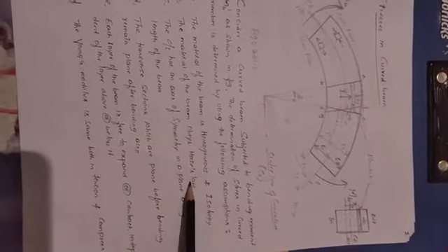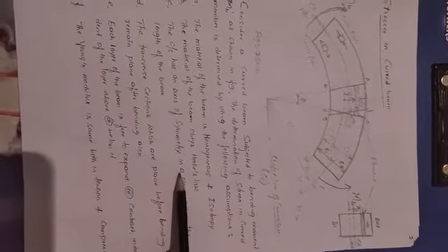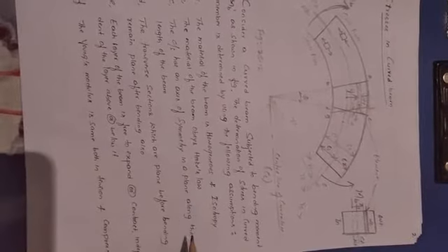Now, before determining stresses in curved beams, we should take some assumptions. As you know, what are the assumptions? The first one is that the material is homogeneous and isotropic. It obeys Hooke's law. A plane cross section, along the length of the beam, remains a plane even after being subject to an action; before applying load and after applying load, the plane remains a plane. Then each layer of the beam is free to expand and contract. In tension and compression, the Young's modulus remains the same.